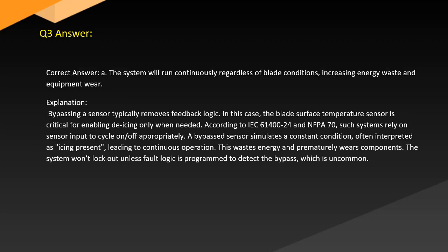Answer. Correct answer, A. The system will run continuously regardless of blade conditions, increasing energy waste and equipment wear. Explanation. Bypassing a sensor typically removes feedback logic. In this case, the blade surface temperature sensor is critical for enabling de-icing only when needed.